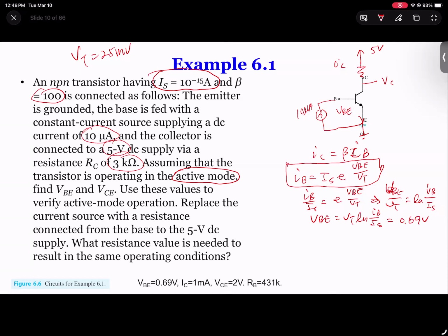I want to stop here for a little bit. It says VBE is... In the earlier part of today's class, I said if VBE is larger than 0.7, it's going to be in active mode. If it's less than 0.7, it's going to be off. Actually, that is really just an approximation. In fact, this transistor is going to conduct around 0.7. It could be slightly less than 0.7 or more than 0.7. That actually, this VBE is going to decide how much current is flowing in.